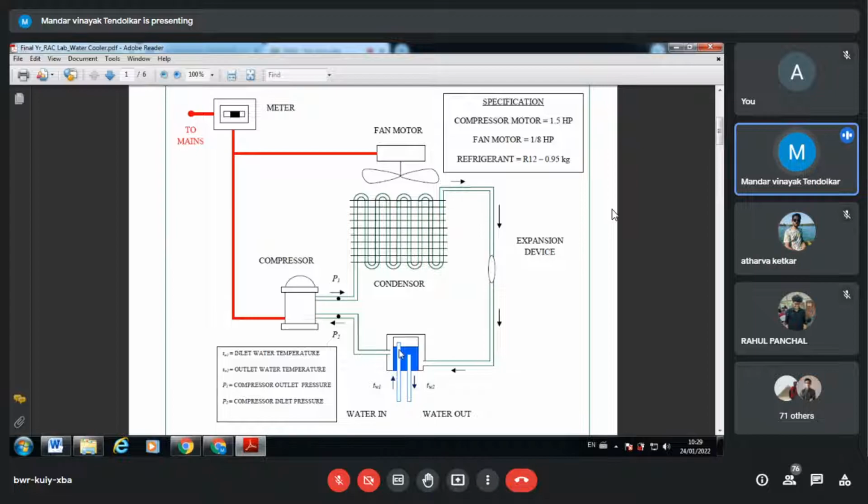And for the refrigerant part, it is a latent one, because as explained in that earlier video, it is a liquid plus vapor mixture which is absorbing the heat from the water. Water is rejecting sensible heat, and what the refrigerant is absorbing is latent heat. Do you agree?